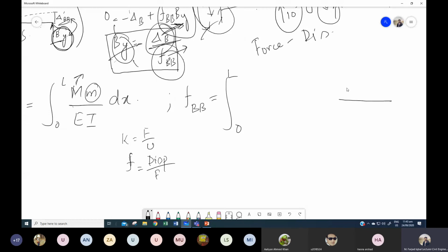So if I have this beam और let's say मैं इस पॉइंट पे फ्लेक्सिबिलिटी निकालना चाह रहा हूँ, ठीक है। और फ्लेक्सिबिलिटी मेरे पास क्या है कि जब यूनिट फोर्स लग रही हो तो उस पॉइंट पे जो डिस्प्लेसमेंट होगी दैट विल बी इक्वल टू फ्लेक्सिबिलिटी। सो आई विल अप्लाई दिस यूनिट लोड and then I will calculate this displacement, and now this displacement is equal to FBB, right?